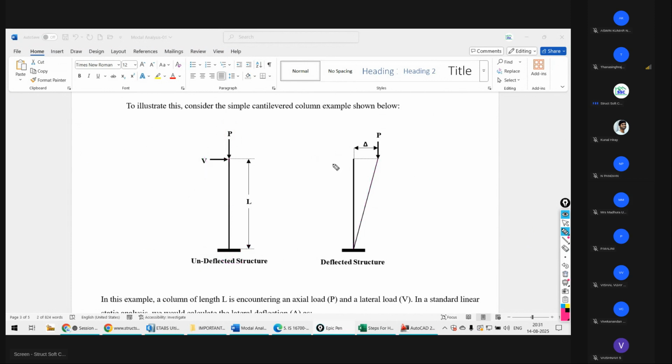Okay, but this is not the end. When you apply the load, your structure is going to deflect in this form, and your building is going to attain this shape. Now the building has attained this shape, so your point of loading is going to be shifted from this point to this point. Actually it will not be here; it will be concentrated from a centroid point, right? But as of now we consider it is shifted from this point to this point. Now this is the fixity.